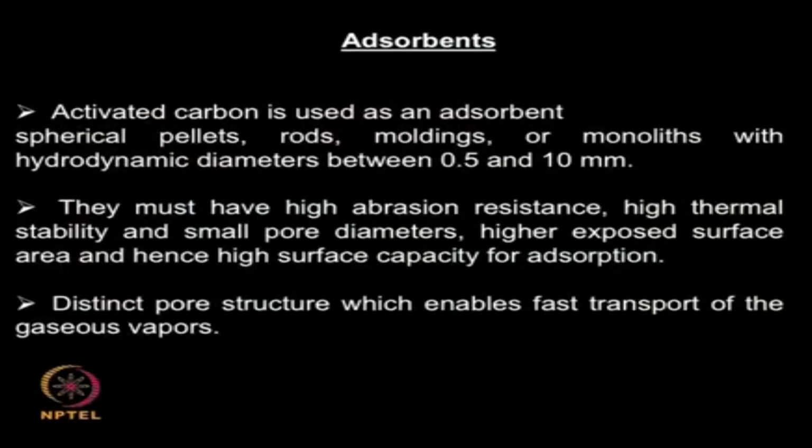So when you move from smaller to larger particles, the surface area goes down, so the activity also goes down. If you use very high temperature for activating your adsorbent, sintering could be a problem which should be addressed as well. There are many adsorbents present in the market, because adsorption is a very old technology, it is well developed.